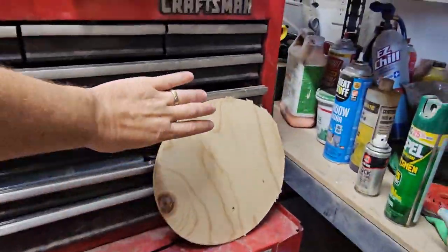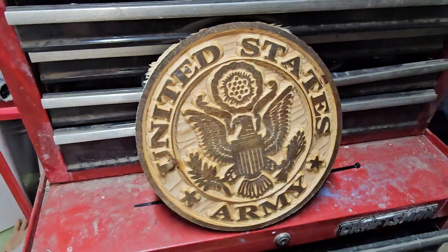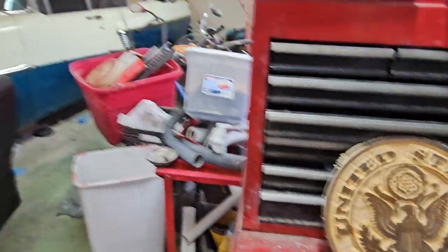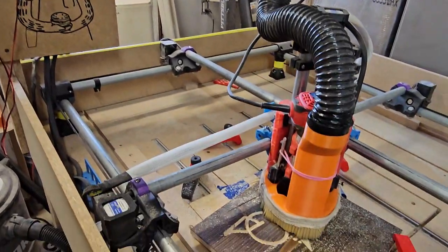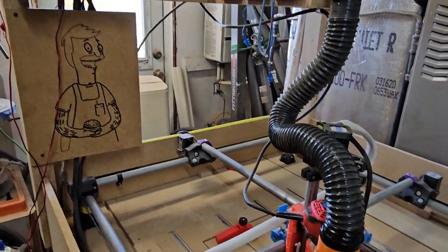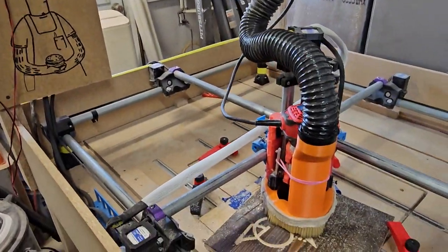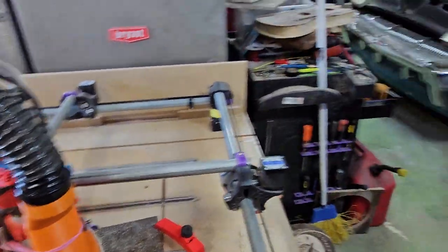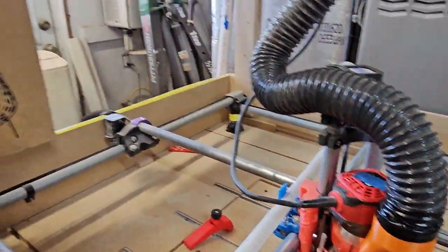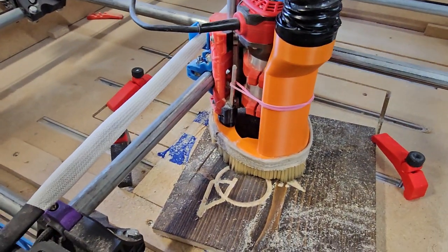And you should end up with, you know, this is obviously more complex than what we're just doing. That's all done with the V-carve, but the same general process, except I did the generation on VCarve Pro instead of using SLCam. But it just generates the G-code, load it onto the board, and then the board just starts feeding directions. There's a couple files you run to get to the plaque stage for the V-carve because you have a bit change in the middle of it and everything else. But that should get you to the point that you can actually create the parts that you want.